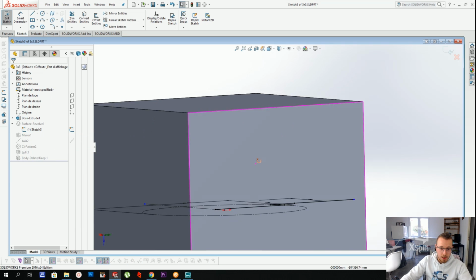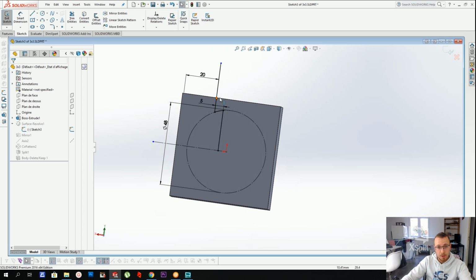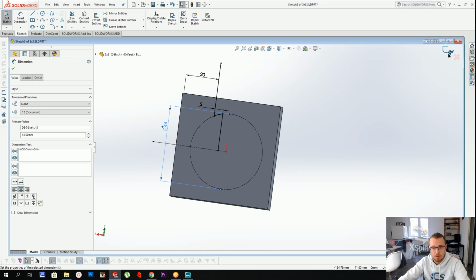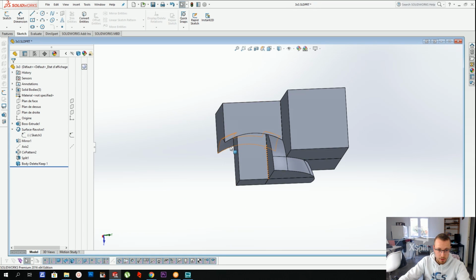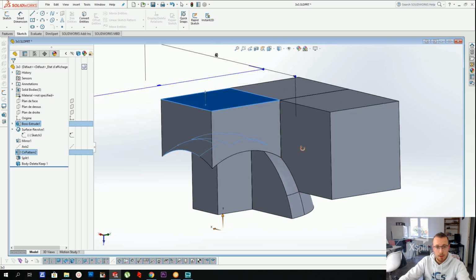So what we can do now is maybe add a little bit more room for the screw, because the screw is going to go here and there's not much space. So let's reduce the diameter to 44. That seems fine. And now, as you can see, we've got more space for the screw because we've got this whole section right here where we can put the screw.